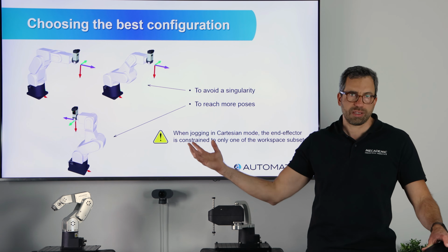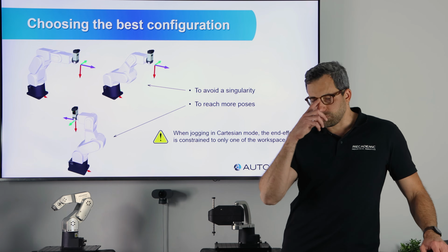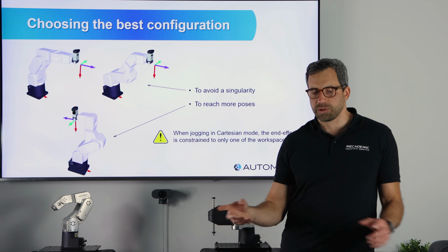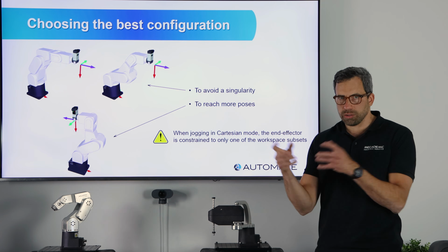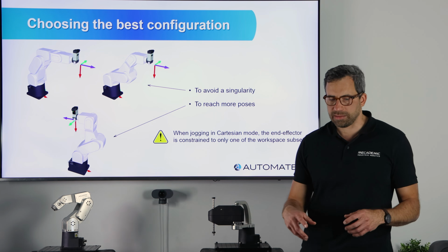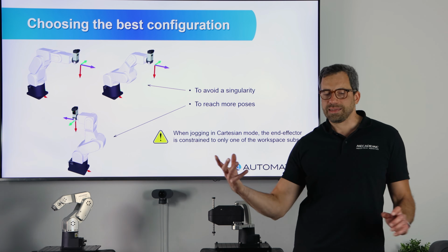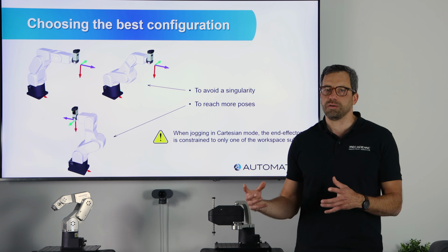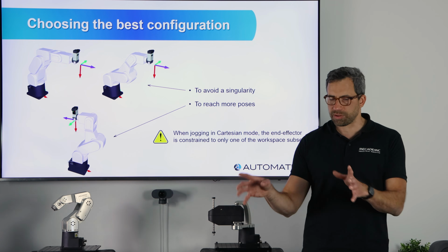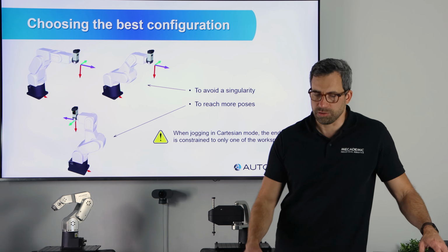It can be RoboDK, for example. In the case of Mecademic robots, you can use RoboDK or other robot software, but use simulation software, because again, when you're jogging, you don't see this. And if you're hand guiding, you see even less of it. Unless you're very well acquainted with the robot, hand guiding is very suboptimal. It's easy, if it works. If you're doing some simple machine learning, it's perfect. But if you want to do something optimal, hand guiding is not the best solution.